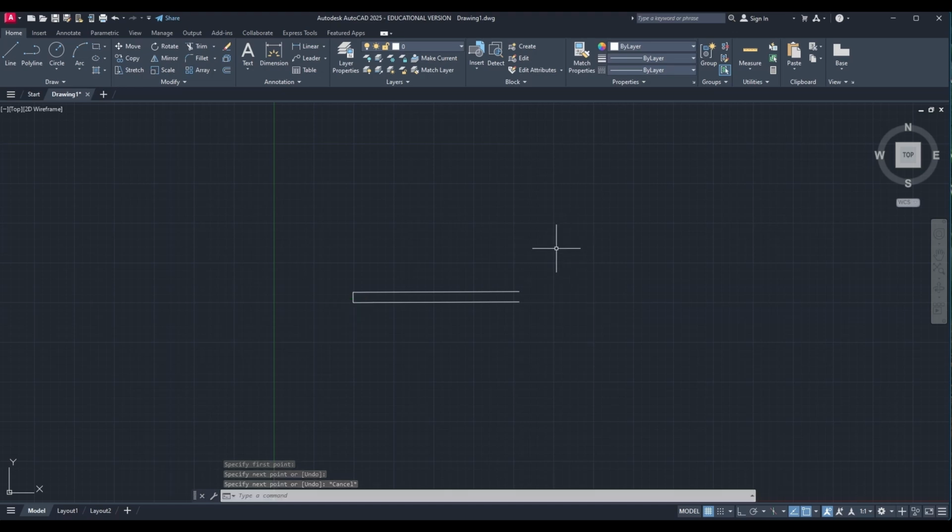Now if you observe carefully, the base is like an inclined line and it's not a straight line. So I need to draw that. For that I will select the line and turn off the ortho so that the angle is 106 degrees. If it is not to this direction, it's to the other direction.